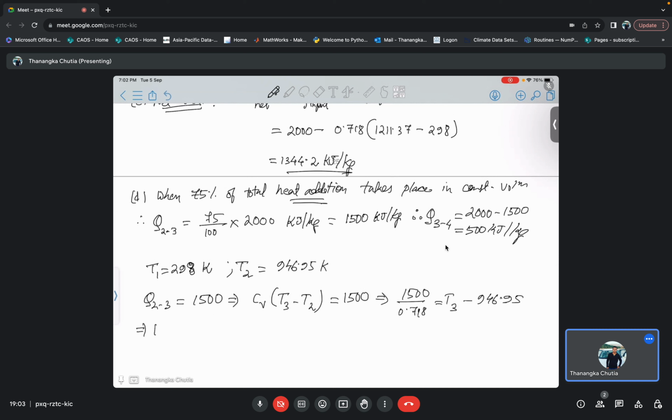So from here T3 will be 1500 by 0.718 plus 946.95. Okay, so T3 is 3036.086 Kelvin. Okay, so this is your T3.